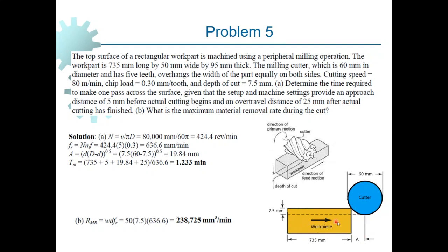And as this workpiece is moving in this direction, the material removal rate increases. From just a small amount, it gradually increases. And at the point when this edge reaches this point, which is just below the center of the cutting tool, then the maximum depth of cut is reached. And then maximum material removal rate is achieved. So it is asking us to compute the material removal rate when the maximum depth of cut is reached, and at that point material removal rate is maximized.